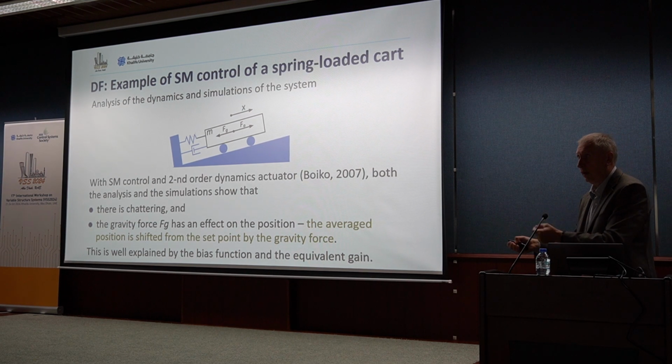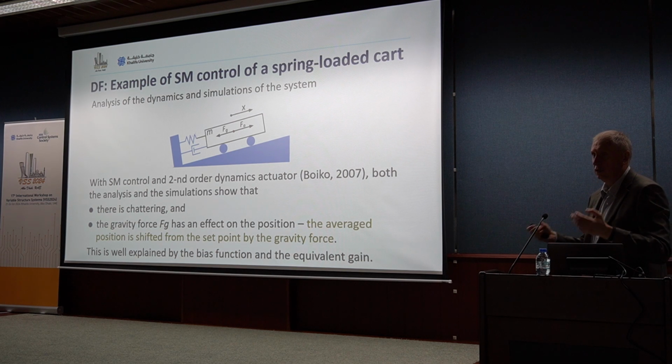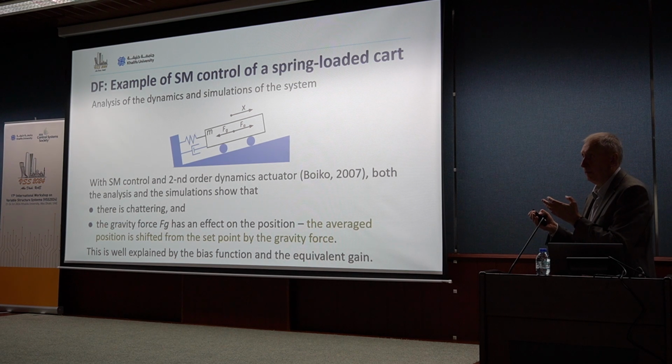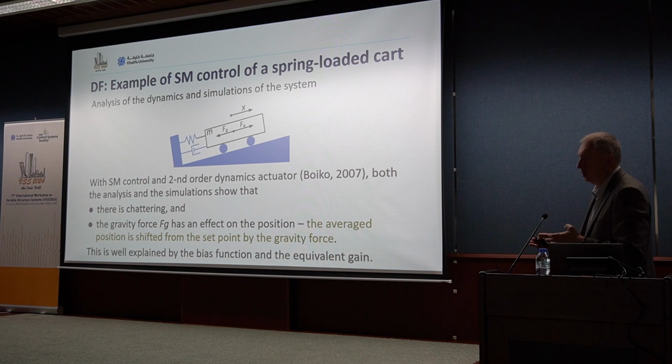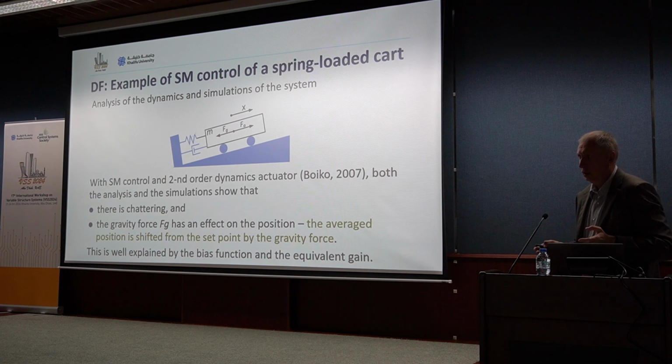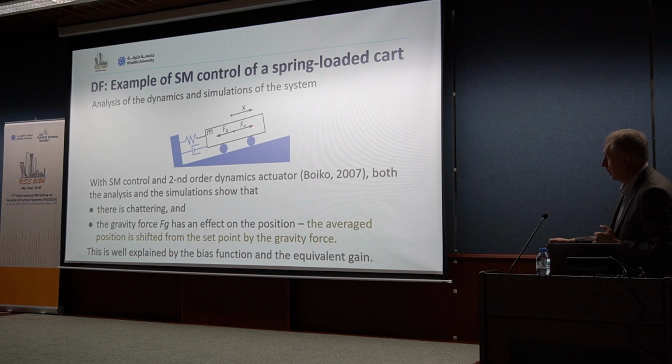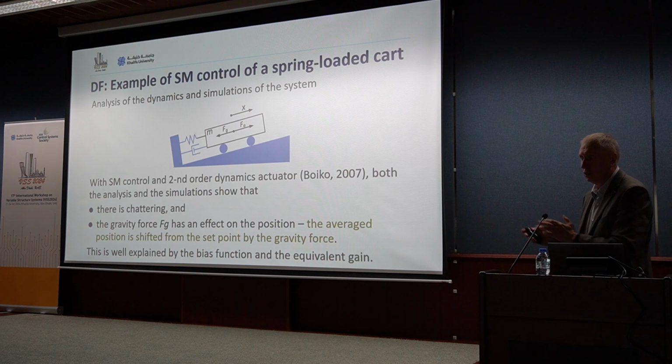But when we have additional dynamics of the actuators, we have chattering. So now our dynamics are described not by Lipschitz discontinuous nonlinearities or non-Lipschitz nonlinearities, but continuous nonlinearities, equivalent gain. We have a displacement, and the simulations clearly show that. We have a shift from the zero position on this curve when we are in this position and try to maintain it at zero by sliding mode control.